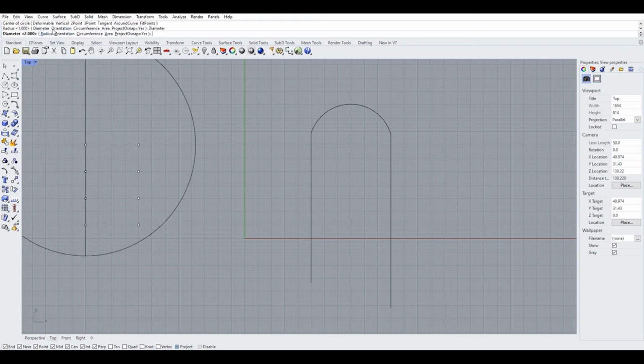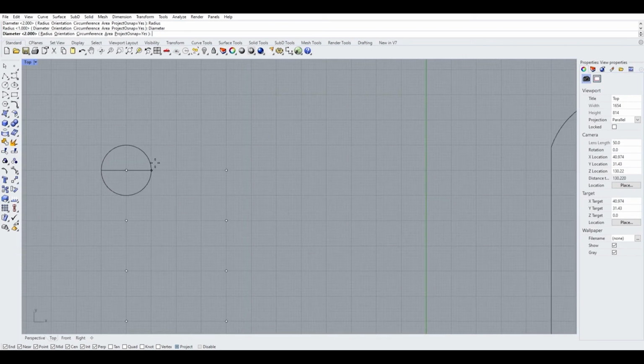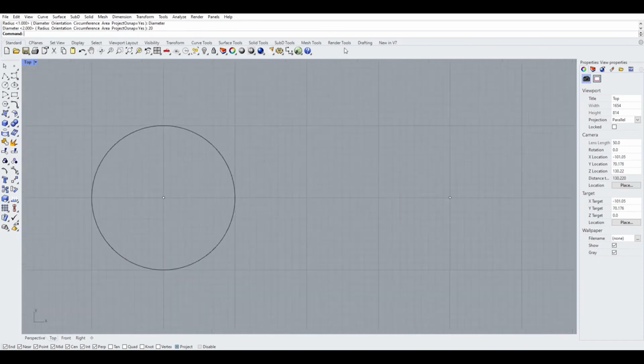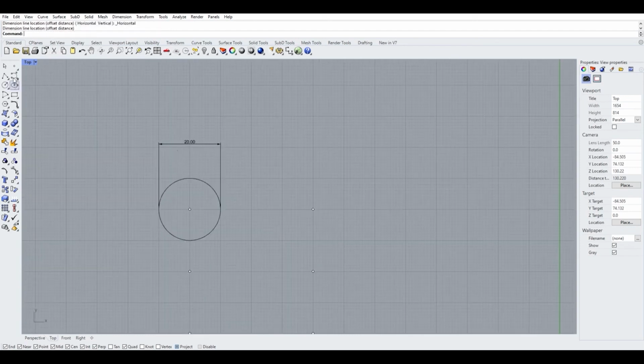You can change that by clicking on the word up there. So if you want to define the diameter, you click on the word diameter, and you can define the diameter. Now, interestingly enough here, you can type in any value you want. So let's say you want a circle with a diameter of 20 millimeters. As I draw the circle out, I can simply type in on my keypad 20 and hit enter. And I'll get a circle with a diameter, I apologize, of 20 millimeters. I can confirm that by turning on my quad snap, using my measurement tools and snapping to the quad, and I see my circle is in fact 20 millimeters. I can do that to any size or shape I want.